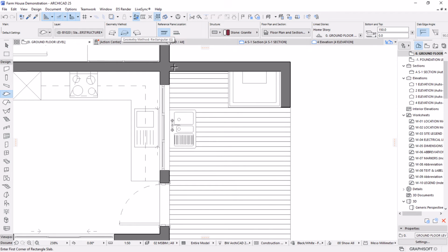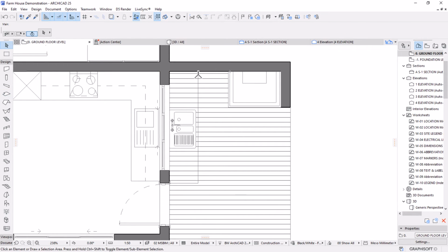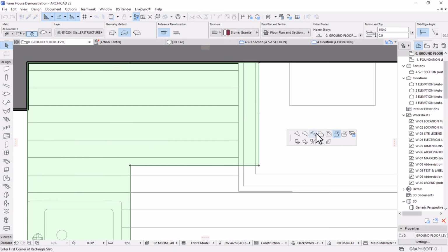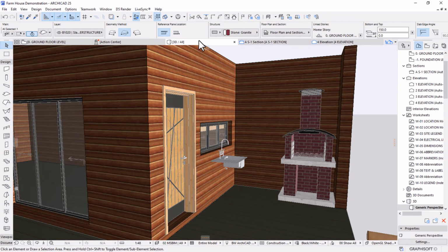Use a geometry method of a square. So I'm going to come here and then draw this direction. The width is going to be 600, right? And then this is going to be 2.3. I can just hit enter. So I have to pick this point and add a polygon again, going all the way to this area, maybe by 750. And then still the width is supposed to be 600. I think let's offset this edge all the way to maybe somewhere here and check on 3D.